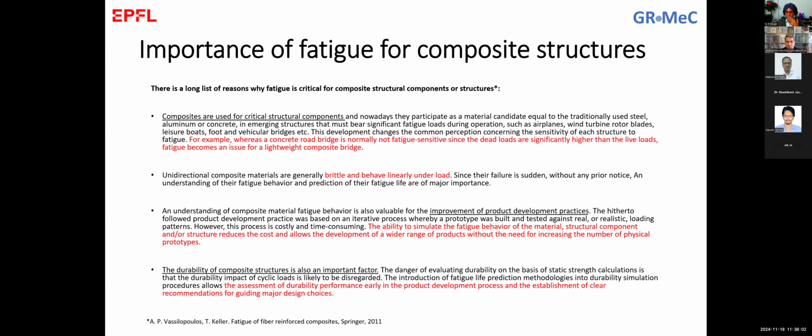When we go then for structural applications like bridges, I have here a comparison of a concrete bridge over a composite bridge, for example. And for concrete bridges, fatigue is not really an issue, and it's not fatigue sensitive because it's so heavy that the fatigue load, which is the live load, is more or less insignificant compared to the dead load of a bridge.